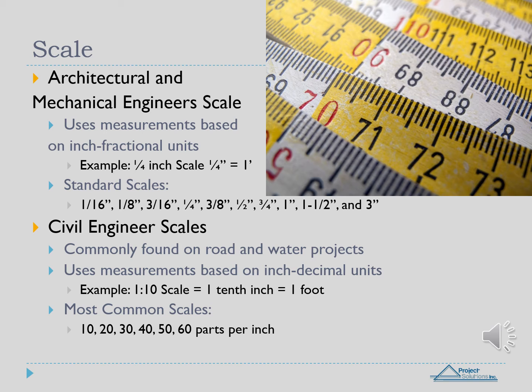The scales will read, as an example, 1 to 10, which translates to 1/10 of an inch equals 1 foot. You will find scales of 10, 20, 30, 50, and 60 parts per inch. Know the scale that you are using when doing takeoffs from plan sheets.